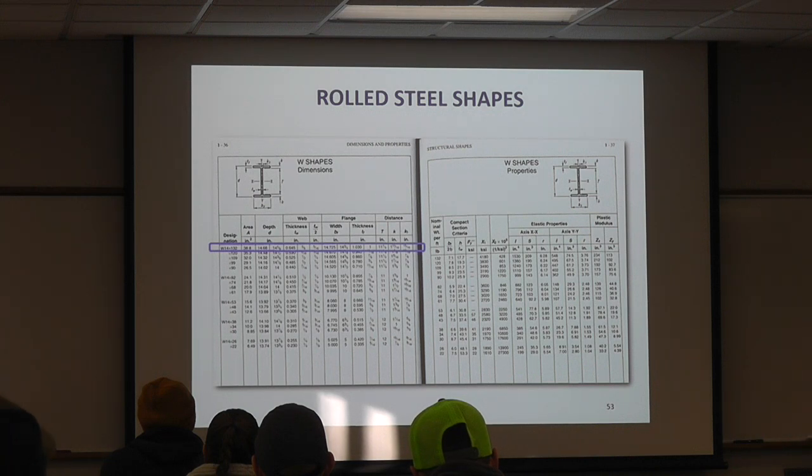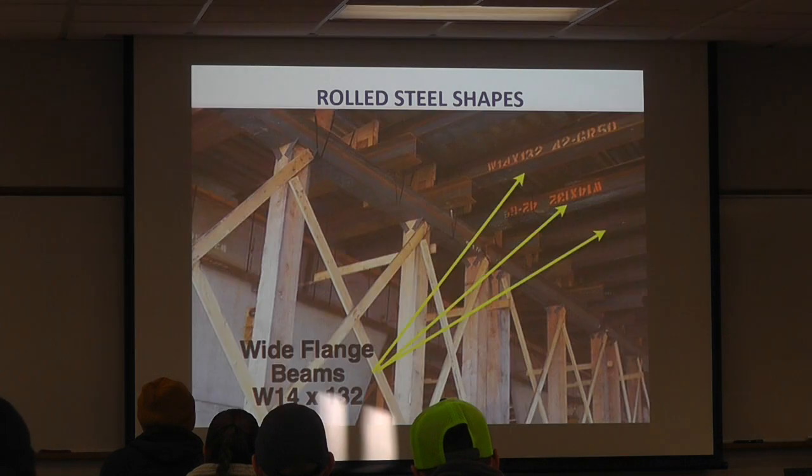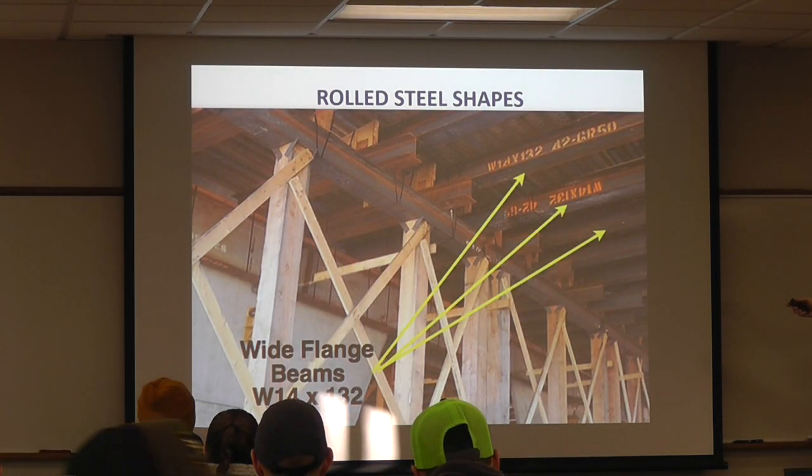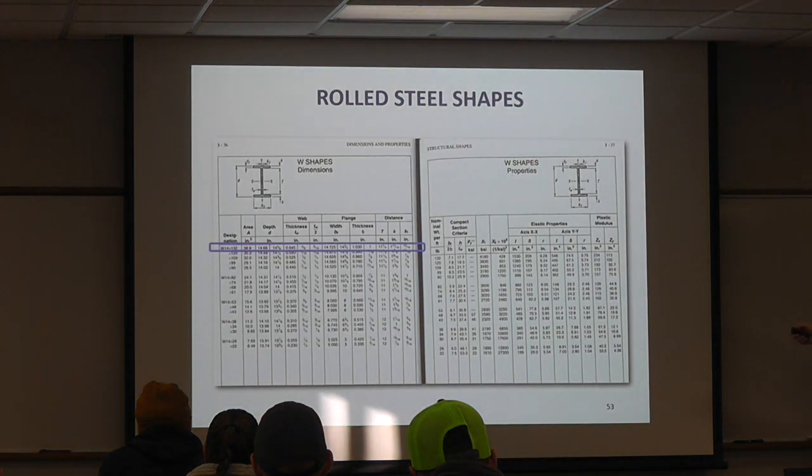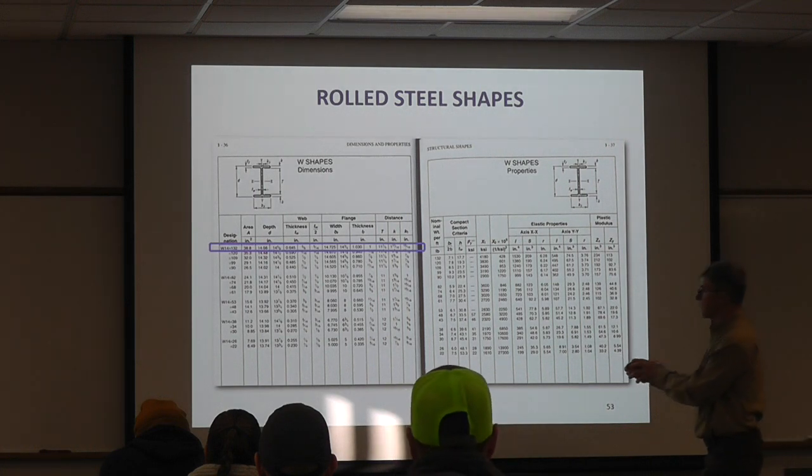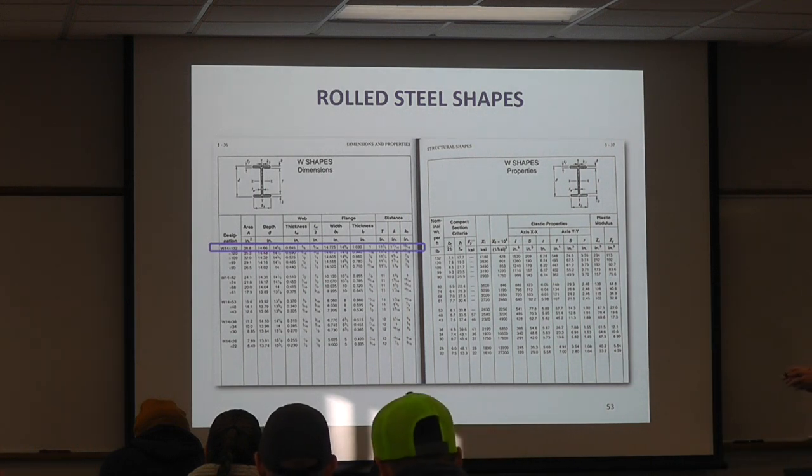If you don't know what size a beam is, it's not like this where it's marked on there, W14 by 132. There are books. This is out of the Steel AISC manual, where you can measure what we have. All of these little things have dimensions. Like here, D is the overall depth of that beam. So if we measured it and it's whatever that says, 14.66, we can say, okay, well, we're probably going to be that beam, or at least we're in the zone.